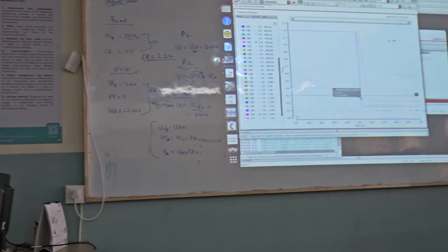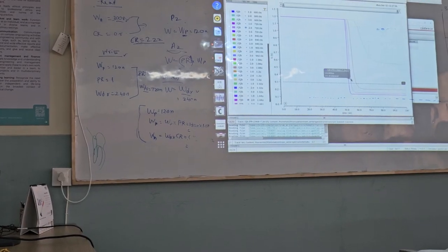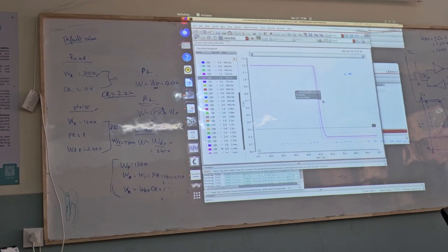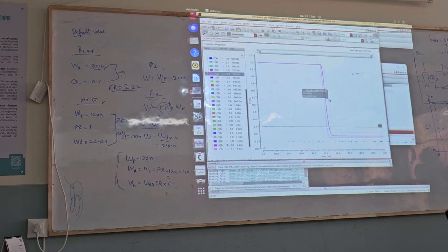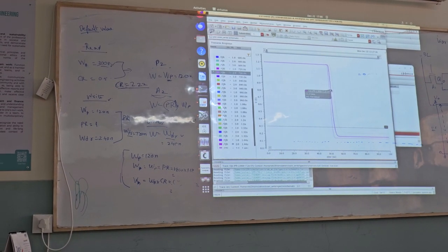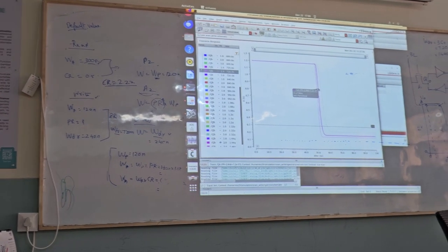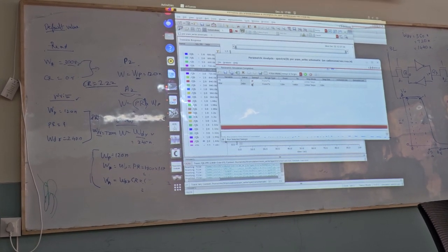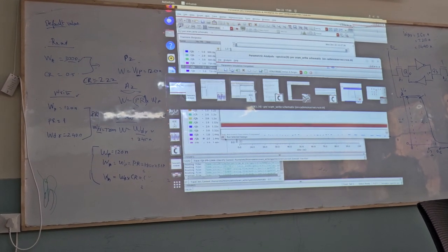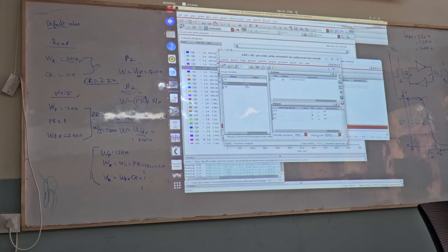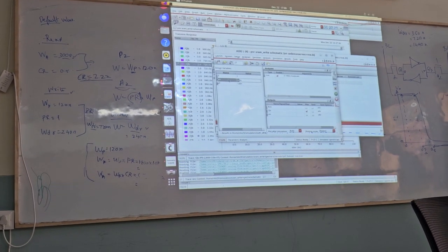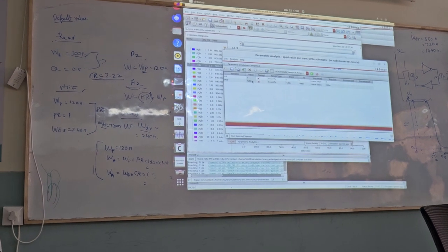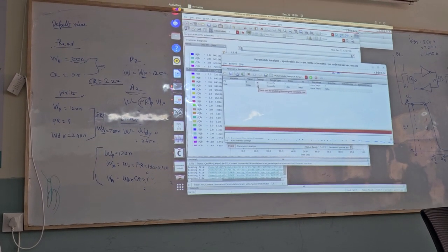So if you compare, the one that we have here is not spending too much area, and we are getting enough pulling down strength as well. Okay, so we'll just go ahead with WDR of 720. So right now, I'll just go back to my ADE and change this to 720, which is the sweet spot. And I don't want to sweep the WDR value further.